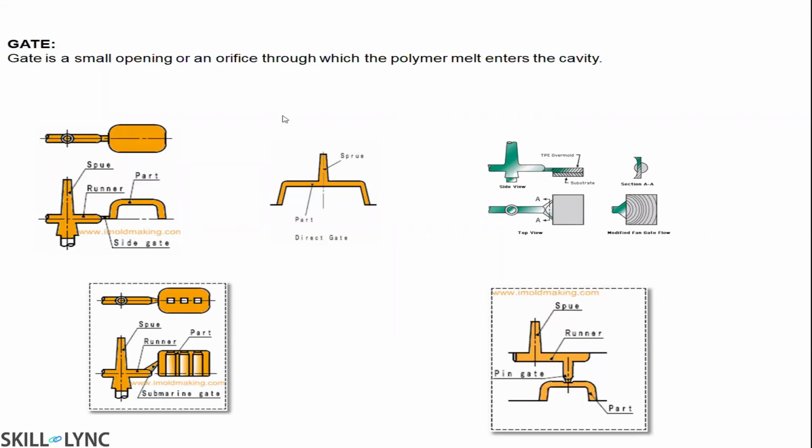On the backside of a bucket, you can see a mark, right? That is called a sprue gate. With all these kinds of gates, we can see the marks. What you can see here at the bottom left is a submarine gate. You can see only a very little mark, and it won't require a secondary operation. But all the others at the top require a secondary operation. After the ejection, someone has to cut the gate to separate the feed system from the plastic component.